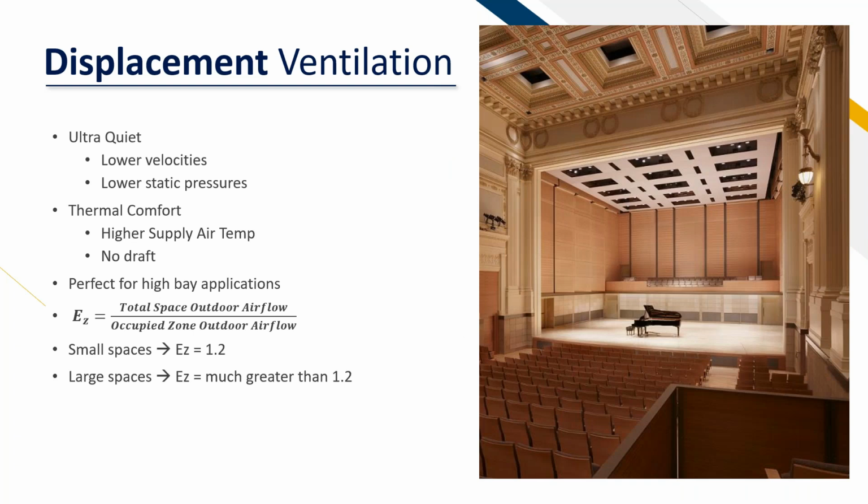It's also a very quiet system, which is a very good benefit for those school applications, as well as what you see here, which is more of an auditorium where there are orchestras or piano playing, theaters, spaces where noise is more of a factor. Displacement ventilation is a great application for that. You can use these sidewall ventilation diffusers to really help deliver air into the space and then have that high return and really keep everybody comfortable with really good indoor air quality.